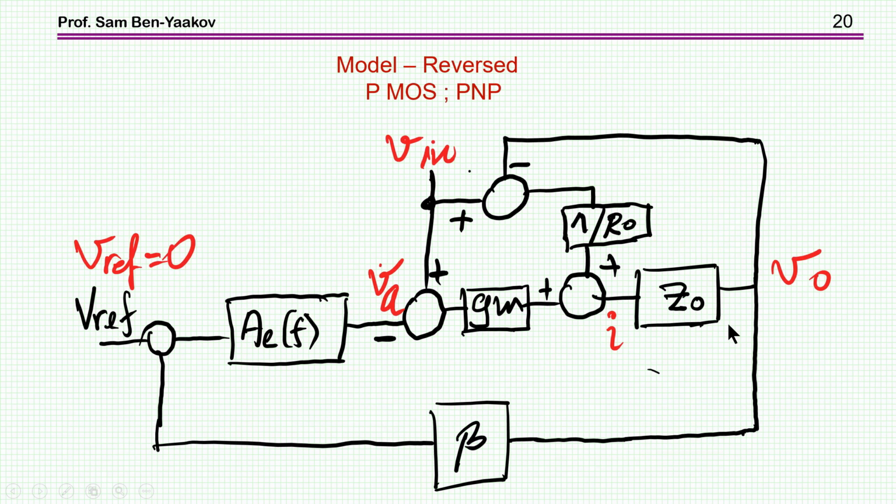So here is the model that I'm putting up for the analysis. This is a control model. This is not a circuit diagram, it's a control. We are talking about transfer function, and these are the signals that we see here. And let me go over it and first of all explain what's the meaning of it. So what we have here is the amplifier. We have the summing of the reference plus the feedback. For the small signal, this is 0 because we are not assuming any disturbance here, although it can be analyzed for that, but not in this analysis I'm talking about.